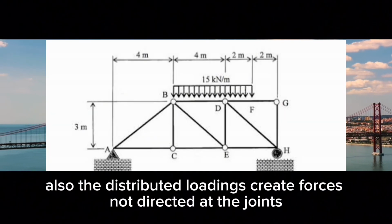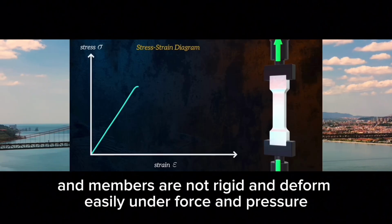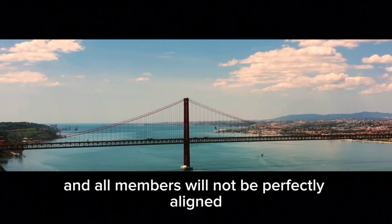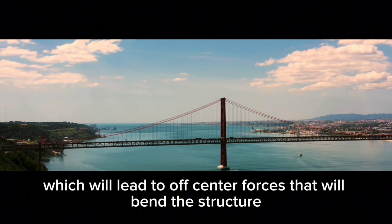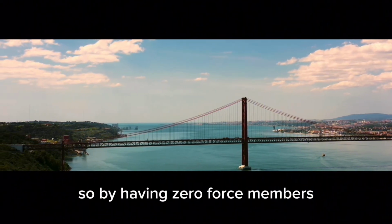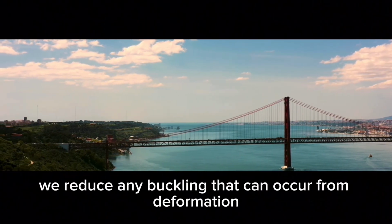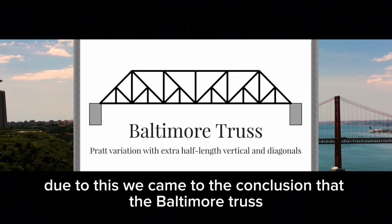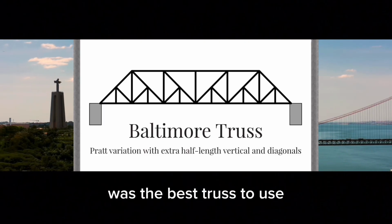Also, the distributed loadings create forces not directed at the joints, and members are not rigid and deform easily under force and pressure, and all members will not be perfectly aligned, which will lead to off-center forces that will bend the structure. So by having zero force members, we reduce any buckling that can occur from deformation, creating forces not accounted for, and changing loads. Due to this, we came to the conclusion that the Baltimore truss was the best truss to use.